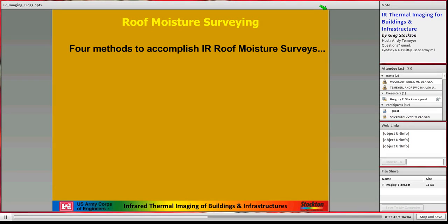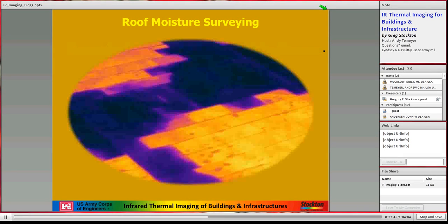And again, not to beat it to death, but putting plastic cellular foams down on roofs without a sacrificial layer of something that absorbs water is bad. You need to put something that absorbs water in it, because it leaks right directly into the building. So the point about infrared is that you're getting 100% of the roof surface covered. Again, infrared doesn't work on every kind of roof. And I see some of my slides are destroyed here.